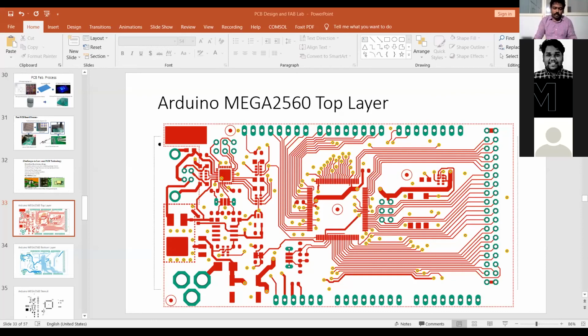There are many types of microcontrollers. What microcontroller are you choosing? Some microcontrollers work for ultra low power, so that you can make very efficient, long duration sensors, especially remote sensors. Some need power handling capacity. So you choose the microcontroller such that it fits your application. These are some mainstream microcontrollers supported, and these are the high performance microcontrollers from STM32. These are the new microcontrollers supported with this software.